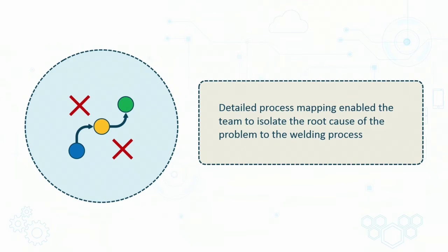Brazers were given no specifications on how to create their welds. They were expected to use their own judgment to achieve a good flame on their torches. Lack of a standard operating procedure, SOP, permitted variation to enter the process. To rectify the problem, an SOP was immediately created to instruct brazers how to achieve the right flame. This eliminated variation and vastly reduced the incidence of pinholes in the PVC.